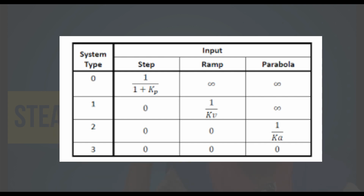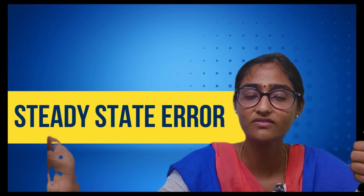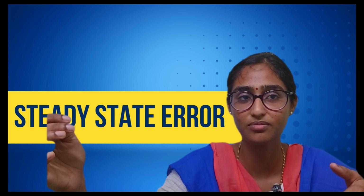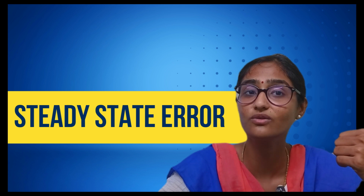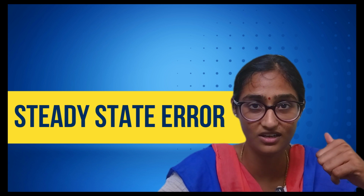There will be a really large error or a really small error which we need to account for when we are designing a control system for any plant or any system. And if it is type 1 and type 2 systems, for a step input we do not have any error at all according to the static error coefficients. But we need to go ahead and analyze this deeply because frankly there isn't a system which has zero error. We need to understand that very clearly.